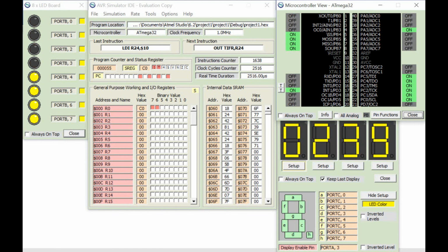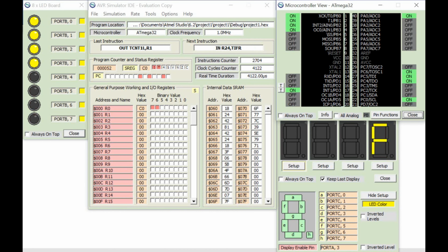What happens if we turn off pin D3? INT1 is not triggered. This is because INT1 needs a rising edge signal to be triggered, meaning it needs the switch to be changed from off to on. So let's turn pin D3 back on. Now INT1 is triggered as it receives a rising edge signal. The rightmost 7-segment display panel will display 0 until F. Then the operation continues with task 2. Task 2 will be executed continuously non-stop except when an external interrupt is triggered.